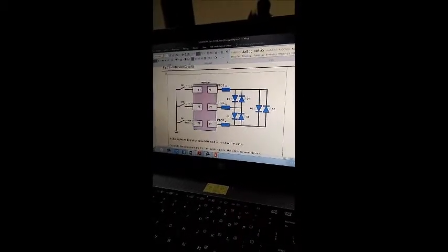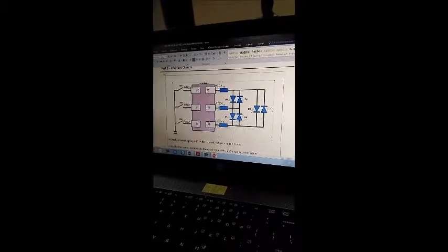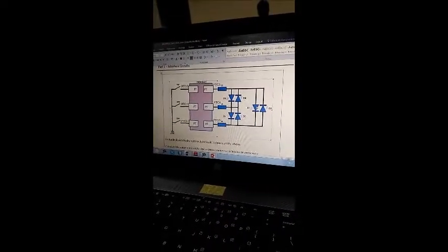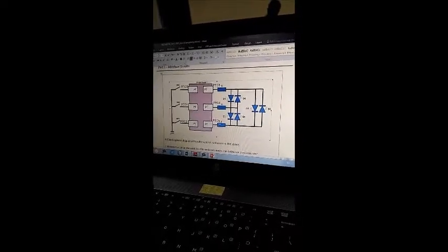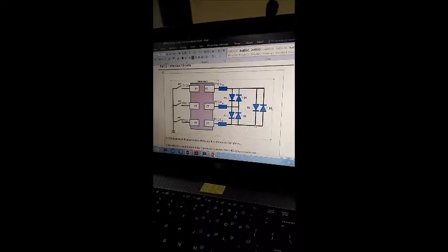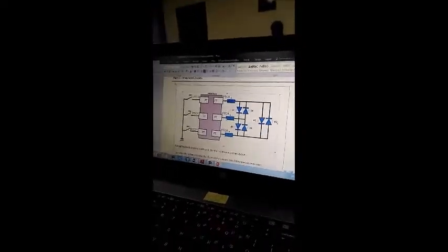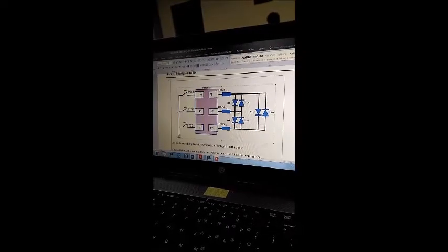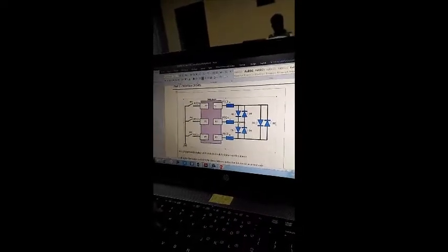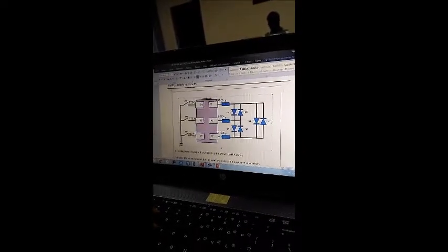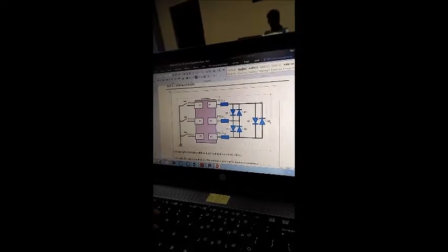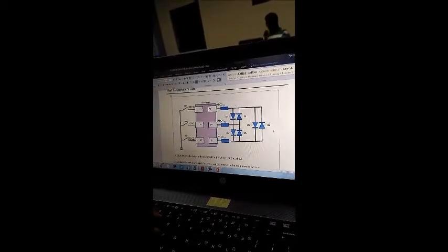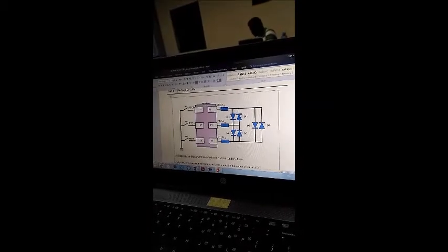So for example, if I want to light up number 1, D1, we will set PTC3, which is output 1, to be 1, high, and we will set PTC5, which is output 3, to be low. On the other hand, PTC4, we will set PDDR to 0 as an input, so that this will be treated as high impedance. The current will only flow in this way, and therefore only D1 will light up, where D2 is the counter direction of current, so it will not light up. So this is the concept that we are using for the CharliePlexer,